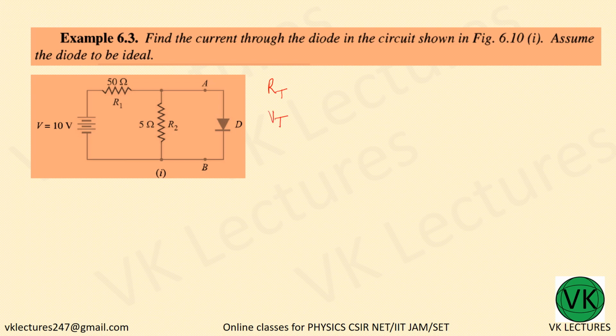Okay, please listen carefully. I am not giving any talk or classes on Thevenin's and Norton's theorem. When we are doing this kind of problems, we will just do one problem and then understand what is happening. Now, to find out VT, Thevenin's equivalent voltage, please listen carefully. Imagine this diode is removed. Remove the diode first. Okay. Then once the diode is removed,